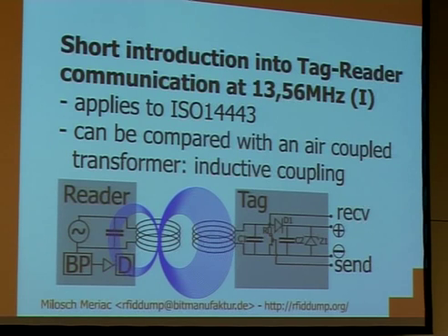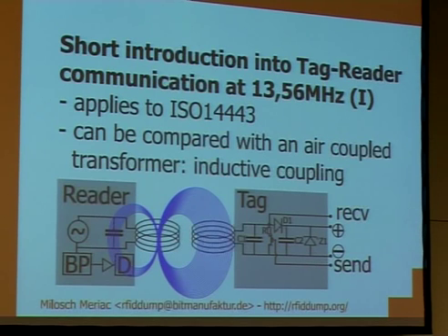And the carrier is received by the tag by using a transformer approach. It's similar to transformers. You have two coils, and it's very much the same as a transformer. You don't have a coil that connects them, but you have an open magnetic field. So the tag receives the field. You see C1 connected on the tag, which makes sure that we are resonating to the field, so you can make sure that you have the highest possible output.